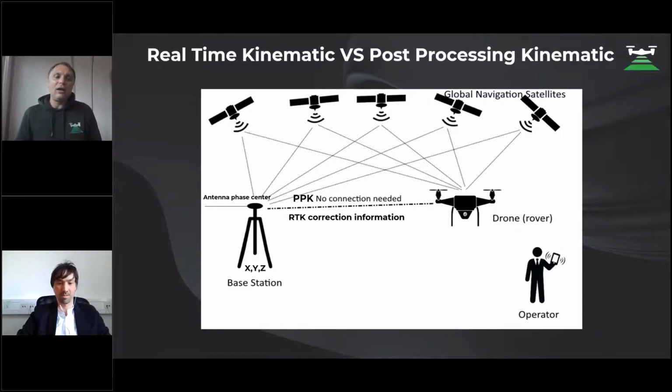In general, everybody knows about RTK, but if we are talking about comparison RTK and PPK, I would say that PPK is more accurate because you post-process data, you can implement additional filters, you can remove noisy satellites, you can implement additional masks just to remove noisy satellites, remove some reflection, and after that you will get more accurate results.